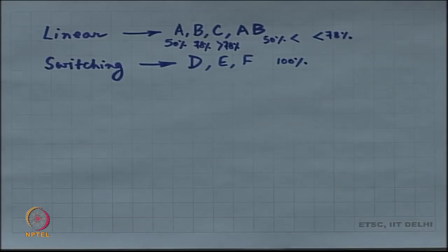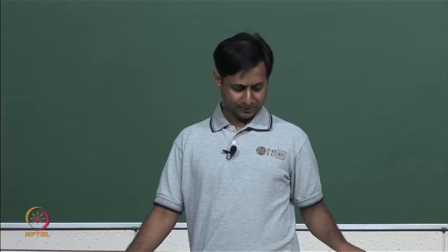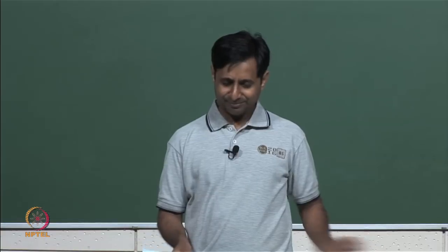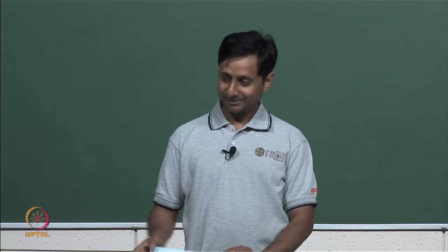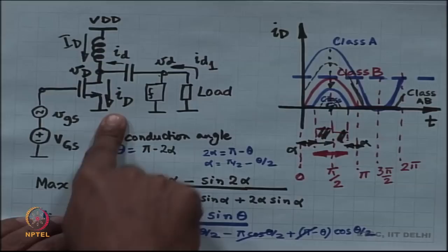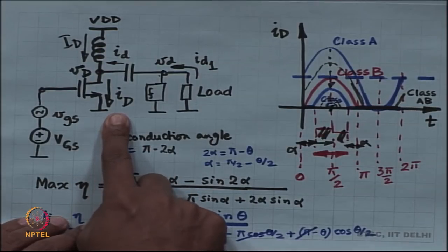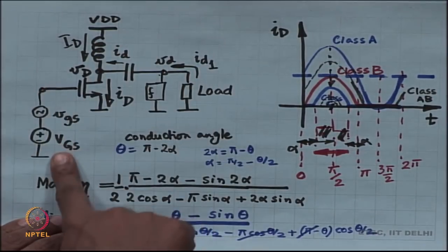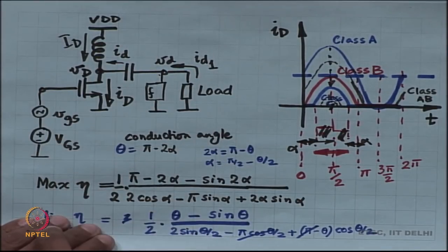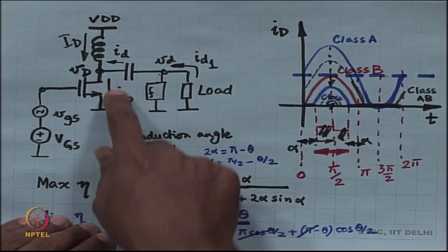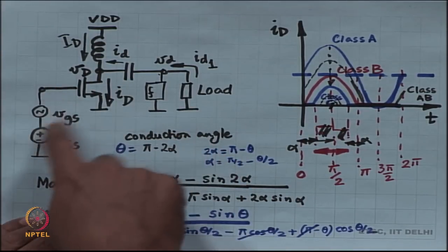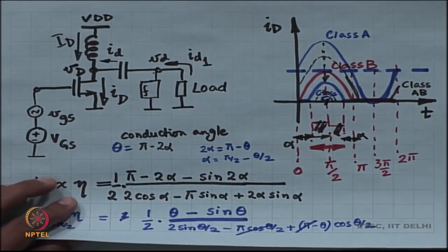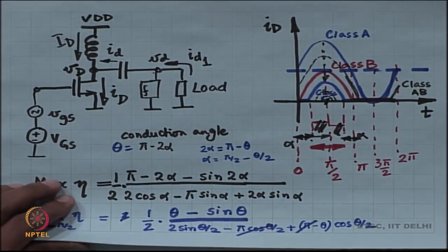these are the different power amplifiers, right, and what is the circuit? The circuit is the same, this one, right, there is nothing different, it is the same circuit, you are just playing with the VGS value, and in case of the switching amplifiers, you change the input signal as well, you make it a pulse width modulated nice huge digital signal, right.